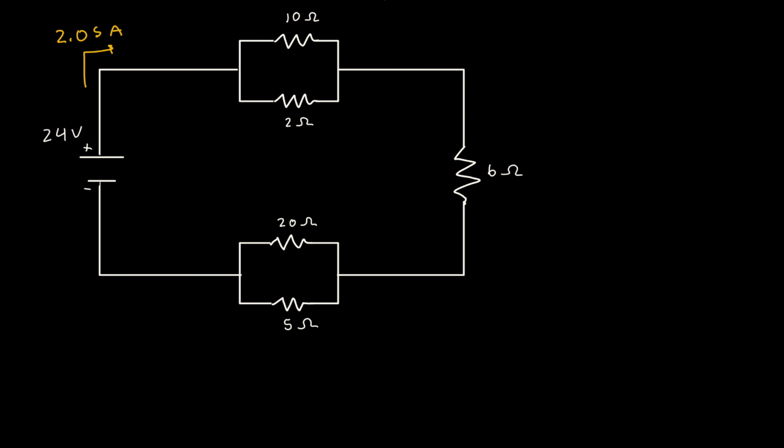All right, so let's say we wanted to find the specific amount of current that is flowing through each of these resistors. Well, first we want to label each of these resistors. So this is R1, R2, this guy over here, R3, but we don't really have to worry about this guy since it's already in a series. We know 2.05 amps is flowing through this guy. So this is R4, and this is R5. So if we remember, when we were calculating our voltages, this guy over here was 8.2 volts, and this guy over here was, I believe, 3.485 volts.